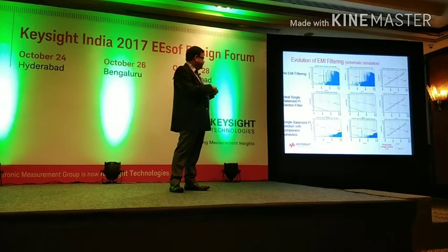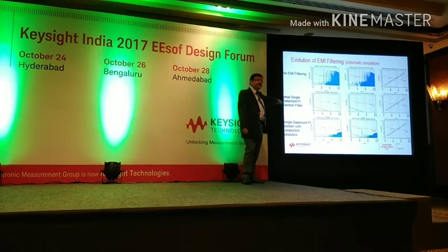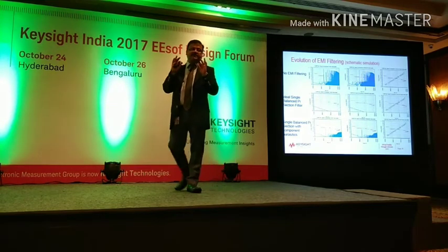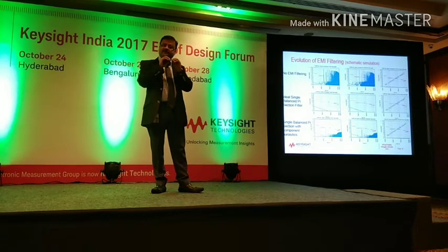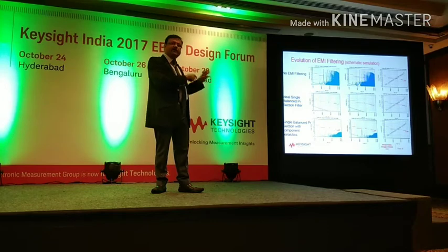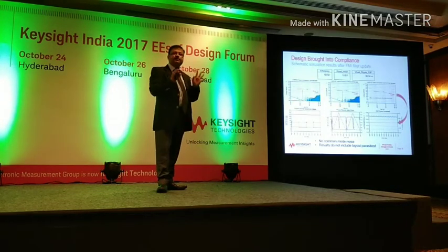And then if you try playing with the filter, there's another type of filter which you can see with physical parasitics. This is an ideal filter, the center plot, with ideal inductor, ideal capacitors. The bottom one is with inductor parasitics and capacitor parasitics, and suddenly you can see one nice plot. But again, you're complying to the standard, no problem. So EMI filtering is doing its job.